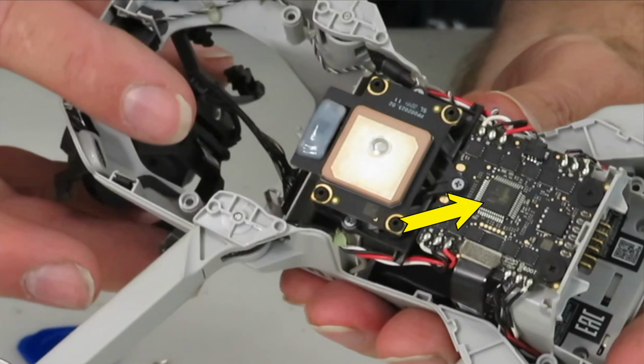Okay, let's talk about Flight Control Module and sensors. The FCM takes your commands and translates them into precise actions using speed controllers for each motor, GPS satellites to track the position of the drone, an altimeter, usually barometric, to determine the altitude, gyroscopes and accelerometers to detect motion, a magnetometer, which is a fancy word for a digital compass that needs to be calibrated regularly, by the way, especially when flying in different locations.